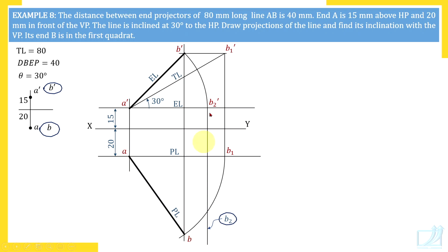What is that? Top view. So A dash B dash is front view and AB is top view. Is this drawing complete? Not yet. When you rotate PL, you got a new point. Now through this point, draw a horizontal and vertical line. Vertical line is already there.